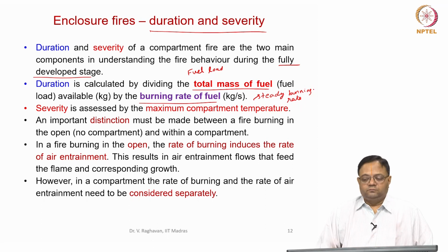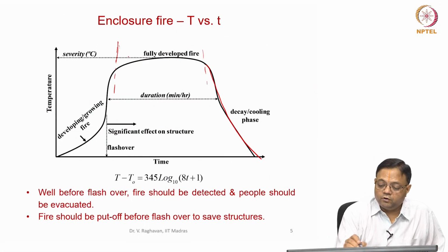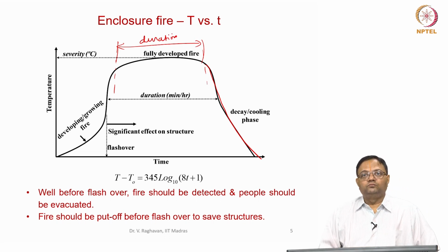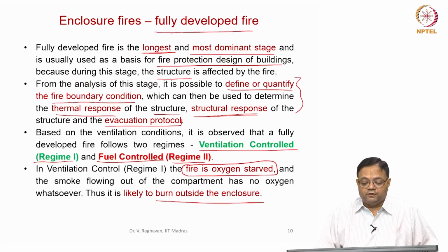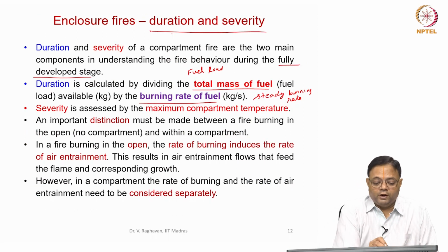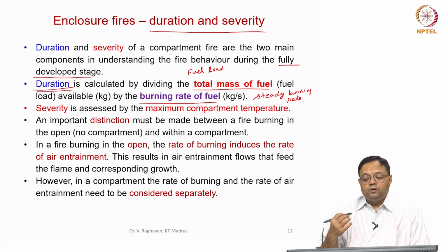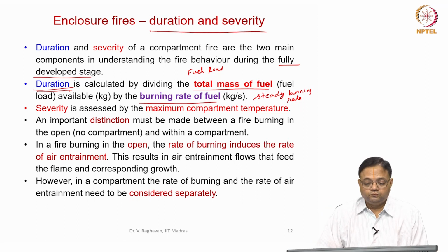So, duration, again if you go back to the curve, this is the fully developed fire duration. This is the maximum duration also, the longest period of burning. So, this duration, because it consumes the material not at a very high rate, is defined as the total mass of the fuel which is available divided by the burning rate of the fuel.